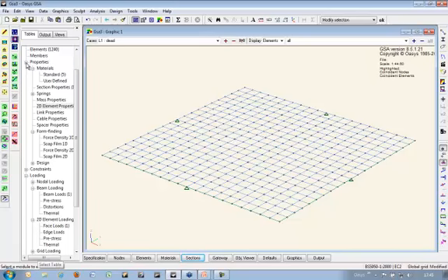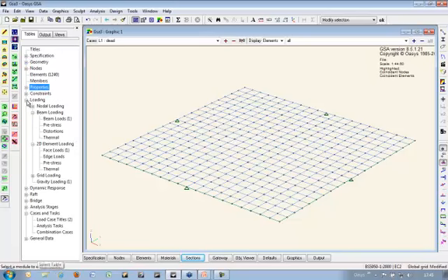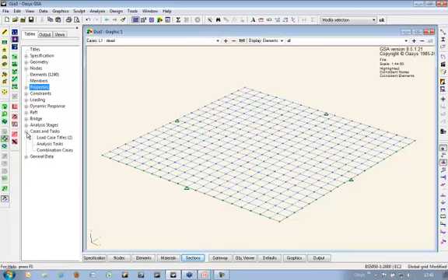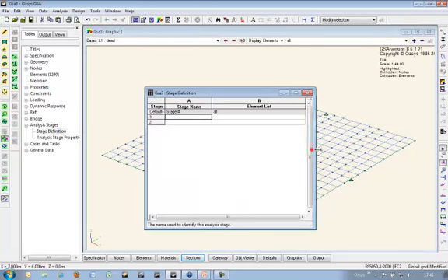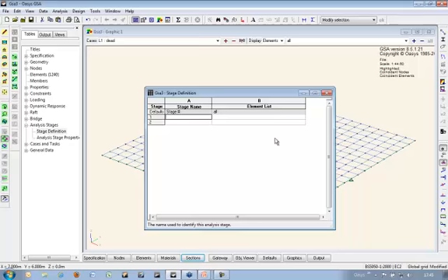Now for the form finding, because I've got shells and beams in there, the form finding will not work with the shells, so what I'll need to do is leave them out of the analysis. So I'm going to use a stage definition, construction stages or analysis stages. I'm going to form find, and I'm going to use the property beam 1 and the static and the property area 1. So what this will do, I'll form find using the beams, and the beams will position the plate or the shell elements, and then I'll analyze the shell elements for static load case.